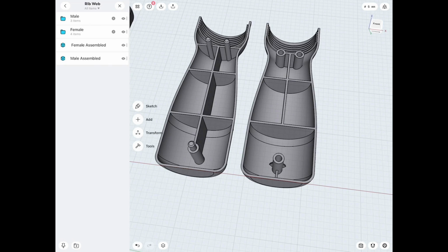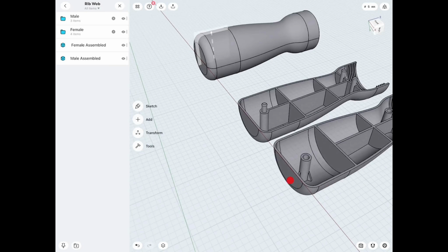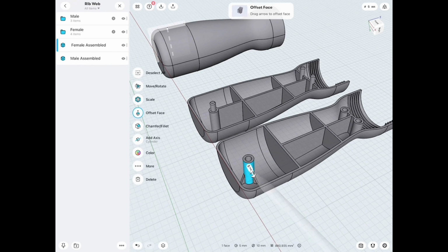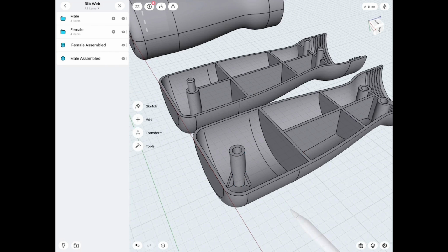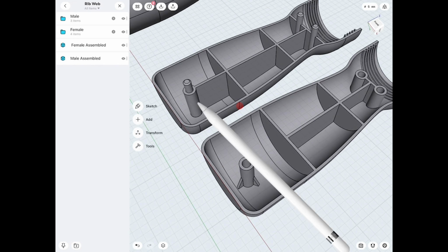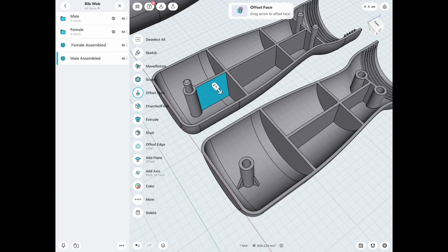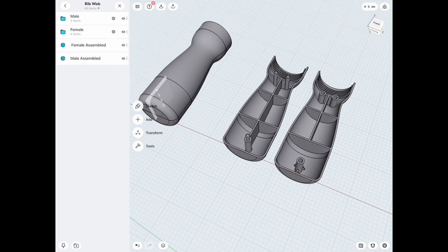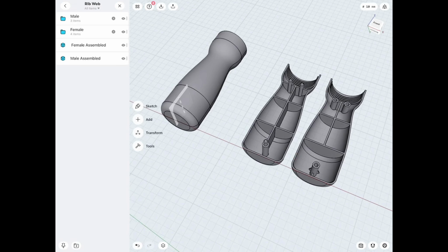The pattern I created is also more a guess. I thought I need at least one in the middle line, and maybe here and here one, not more. I kept this one freestanding because I wanted to show those small fins for modeling, and then here the cylinder, I actually connected the web to it to give you like two ideas how we can add these parts together. And again, I printed this one horizontal, so these interior parts were support free, and then because I was, for me, the part I wanted to study, and the outside I could clean up with sandpaper and some patience.